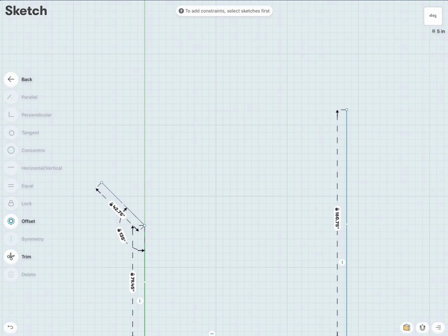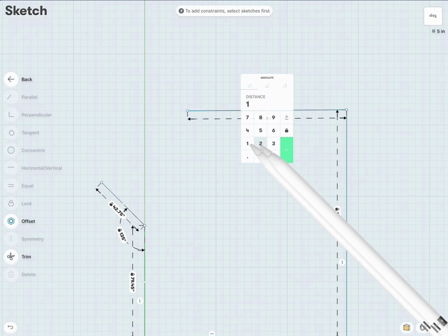You see, that's a way how in a sketch engine, like in Shaper, which is more interactive, you draw, constrain, and then rotate lines versus traditional CAD software where you draw a line and then while you draw it, you say the angle. Because also here we can always go back and change that rotation or the angle. So it's a little bit more interactive. From here, I would like to draw another line to the left. This one is 120.